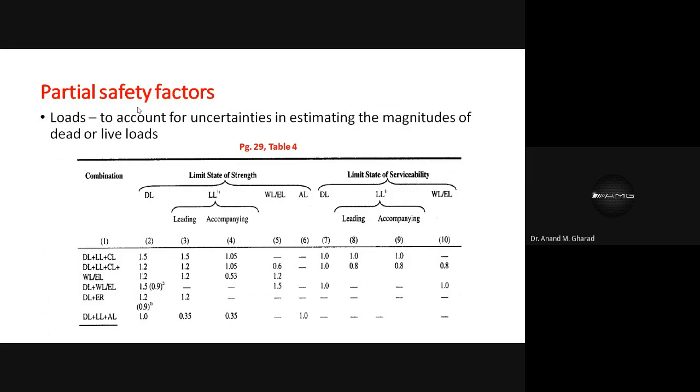Got it? So the factors of safety associated with these major components, if they are applied simultaneously, are known as partial safety factors. That concept has been introduced in your limit state design. This was not true for the working stress design method. So just try to understand these factors of safety which are applied for loads. These are known as partial safety factors for loads.